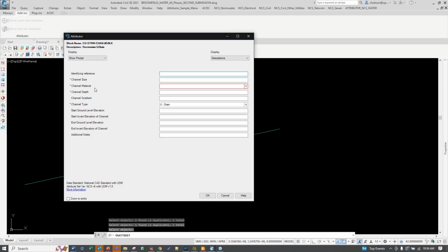and I hit enter, it now looks at the config to get, like, the materials. So there's none of this misspelling and you know what it is. It also shows things like what a description would be as opposed to the code. So that would be the description, but in the GIS you might actually want a code. So there's the codes, and in fact, since we're a GIS company and we put that in, we can show both. So you can display what's in the code and what the description is. You can add help here so that it pops out what it is. It flags mandatory. So this is a huge benefit for folks using attributed blocks.